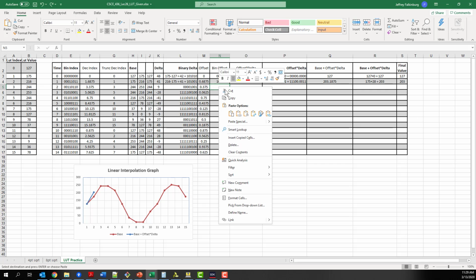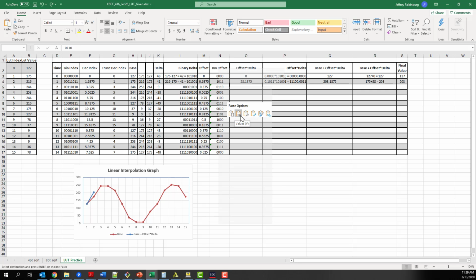Quickly, it's just converting the fractional portion into the binary values. So I'm going to copy those in. 0.375 is 0.011, and we're essentially multiplying by 2 to the 4 power to convert it to essentially a whole number, printing those 4 bits.